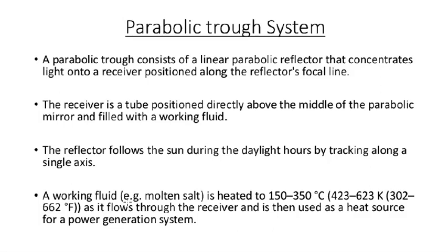The one-axis tracked collectors follow the sun. The collector field can also be formed from very long rows of parallel trough collectors. In the focal line of these is a metal absorber tube, which is usually embedded in an evacuated glass tube that reduces heat losses. A special high temperature resistant selective coating additionally reduces the radiation and heat losses.